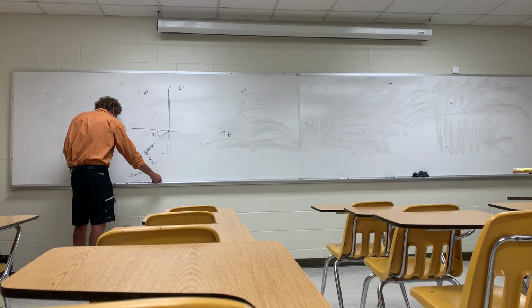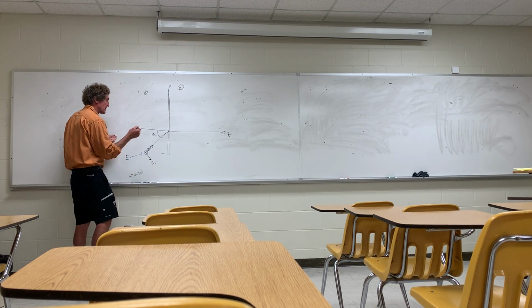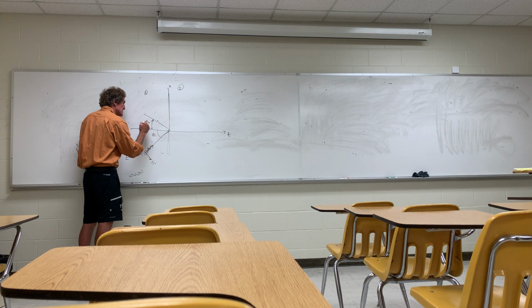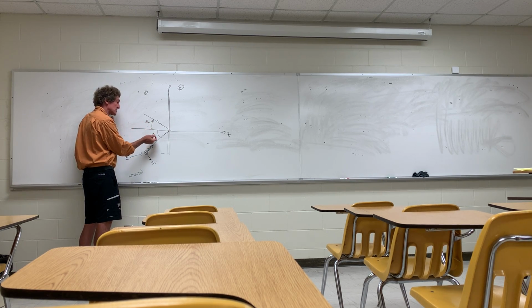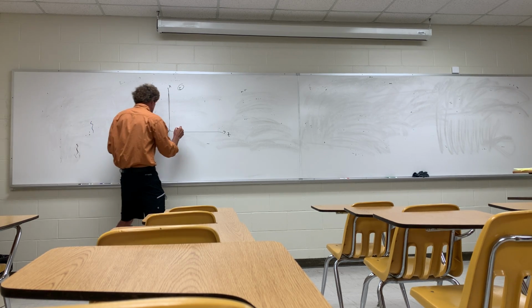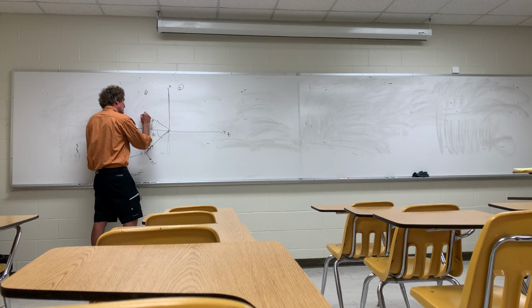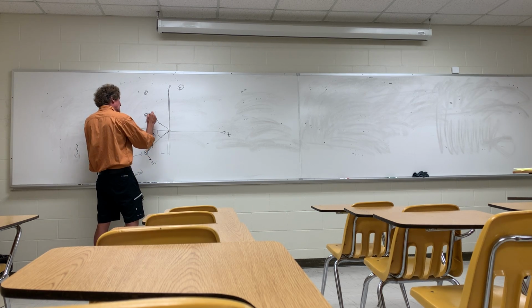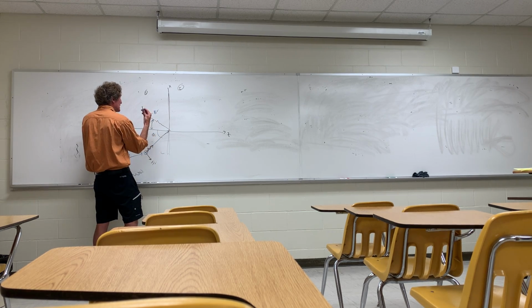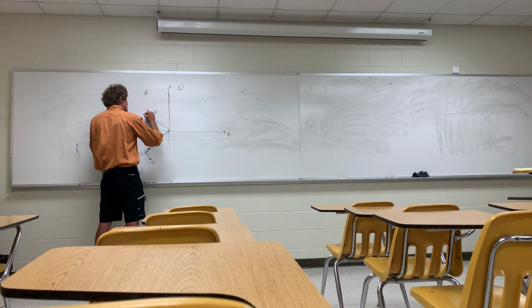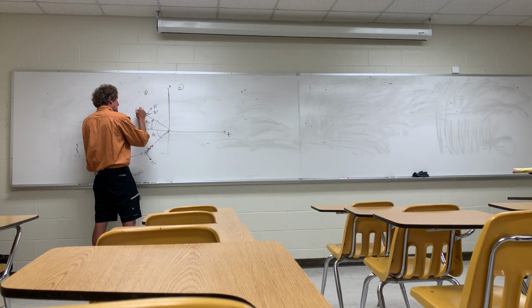When it strikes this thing, there's a reflected wave. We're going to see the reflected wave, the angle of reflection is the angle of incidence. And it's assuming this surface is planar when it strikes. And there's also going to be, here you're going to have an electric field coming out of the board. This would be the incident field. This is the reflected field coming out of the board. And you'll have an H field too, so E cross H is the direction of propagation. And it's propagating that way, so H is up. Because it's propagating this way.